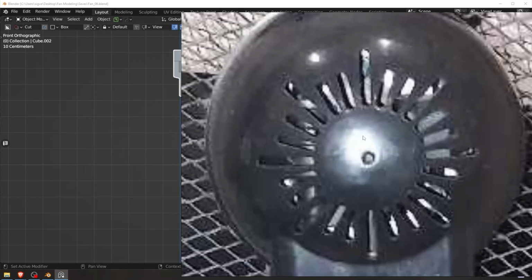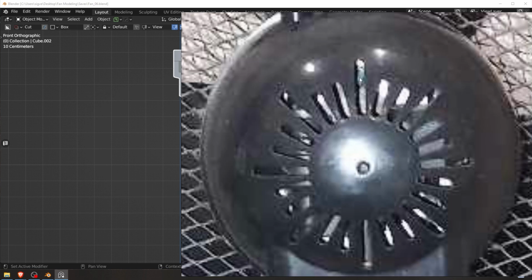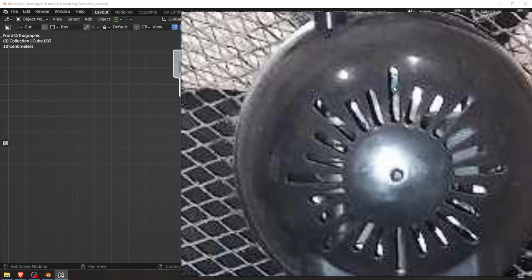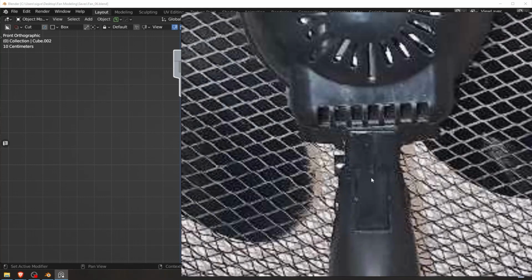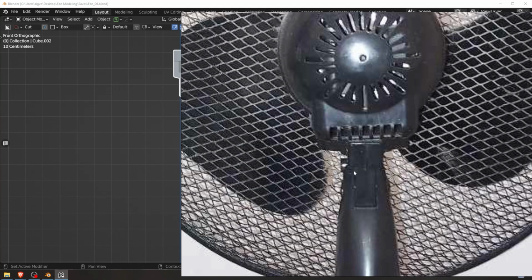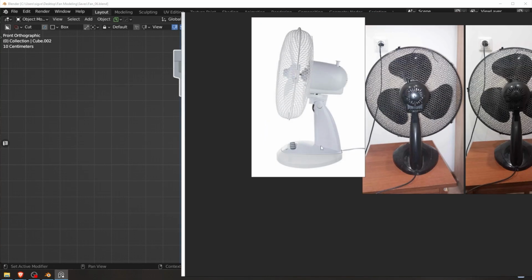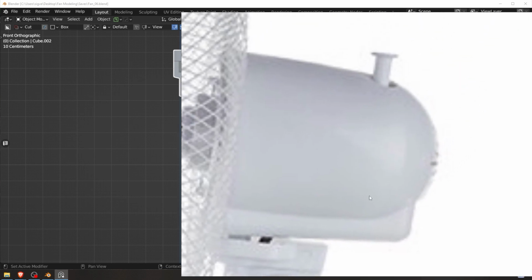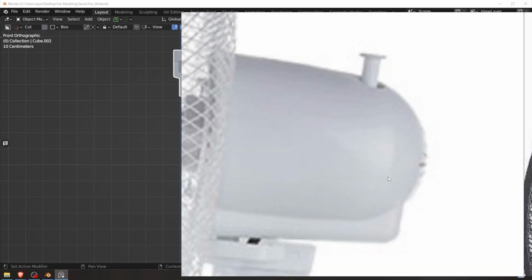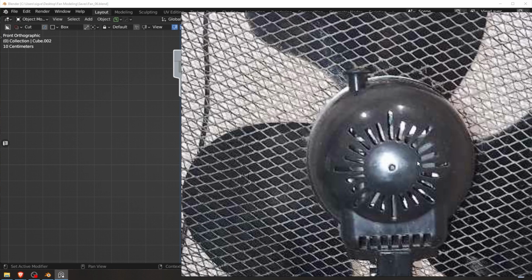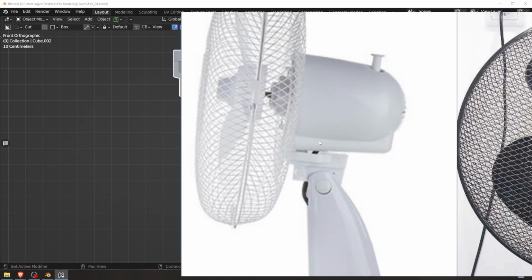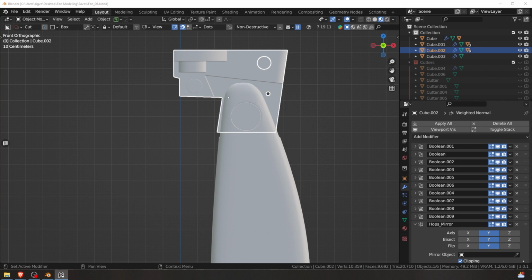And for the back part, for this part right here, we're going to just use radial array and do the cuts. We'll probably do 1/4 of it and then just duplicate them in all 4 axes. That's just simple rectangle cuts. For now we're going a little bit high poly. We still sometimes care about polygons, but we're doing high poly. Later we'll bake all this detail. It won't be real geometry. So yeah, let's jump into this.